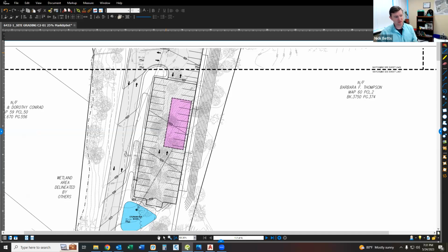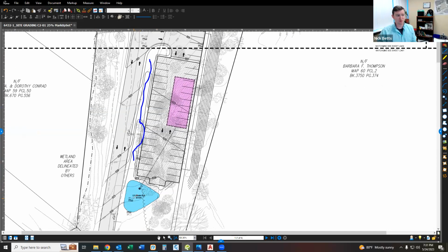So we're taking everything to the south side, or the Mass Ave side, of that, and we're capturing that as one treatment area. So the water will shed from that wall back down towards Mass Ave over this gravel parking lot, get captured in this swale, just some grading, the topography. It enters into the stormwater basin, which again is just a shallow basin that can be planted. So it could look like a rain garden with pollinator species, whatever you need.